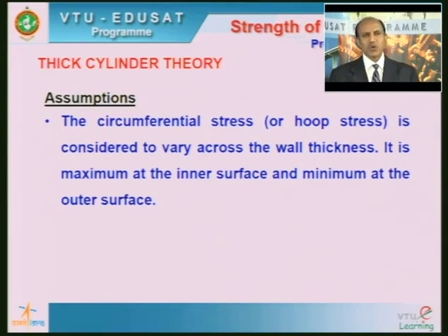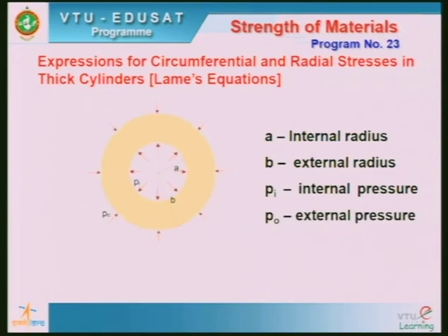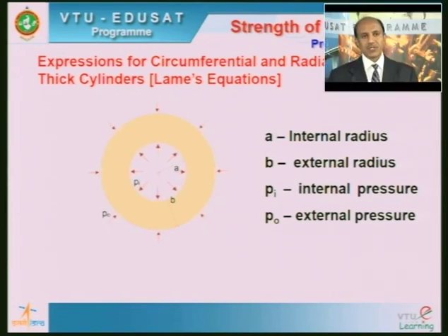The bookwork is very, very important, and quite important also. This is also called Lamé's equations. Please understand, we are trying to derive two expressions. In the beginning we did mention that the thick cylinder is subjected to a triaxial state of stress, but we are more interested in calculating the circumferential stress and radial stress in thick cylinders. Coming to calculation of sigma L is a very simple matter.